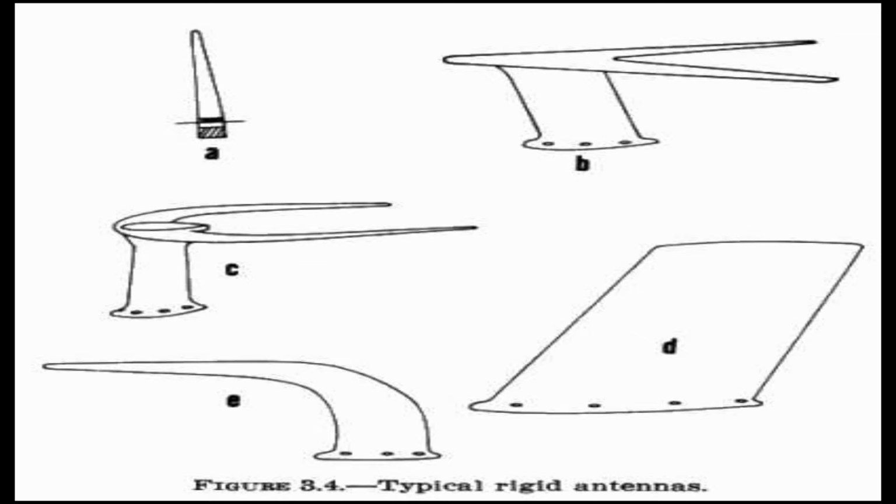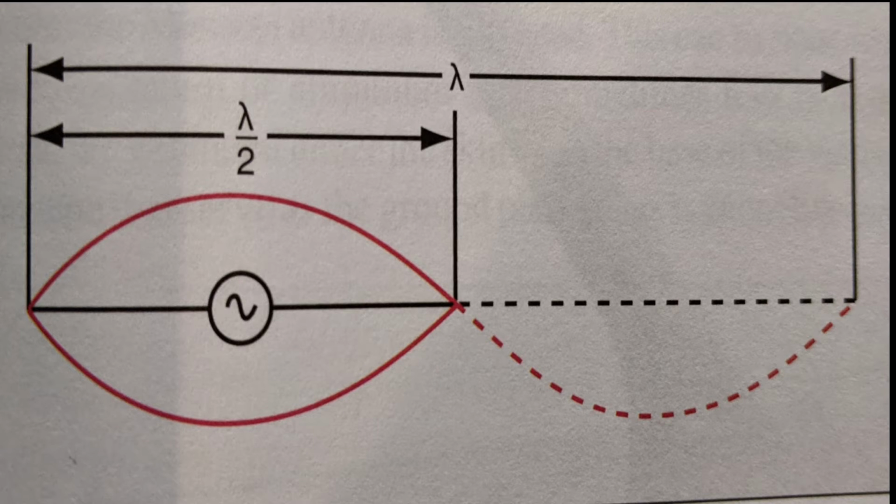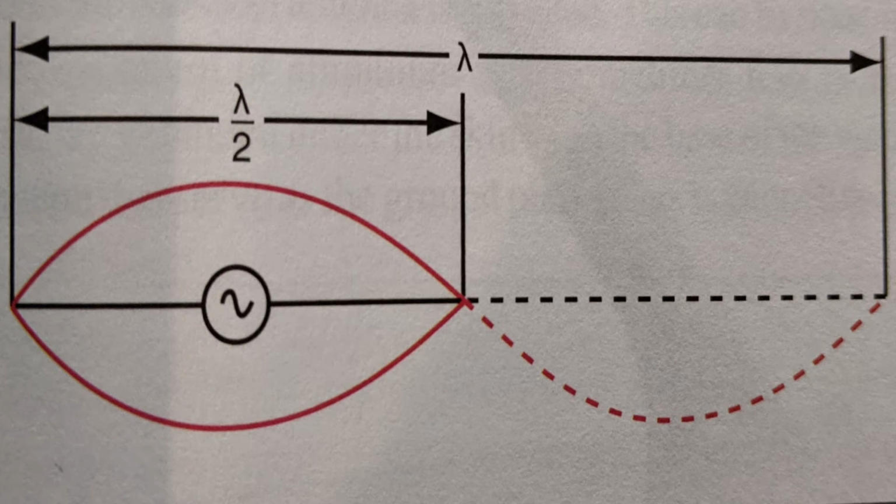Length of the antenna. When an AC signal is applied to an antenna, it has a certain frequency. There is a corresponding wavelength for that frequency. An antenna that is half the wavelength of the corresponding AC frequency is able to allow full voltage and full current flow for the positive phase of the AC signal in one direction. The negative phase of the full AC sine wave is accommodated by the voltage and the current simply by changing the direction of the conductor. Thus, the AC frequency flows through the entire wavelength. This produces the strongest signal radiated.